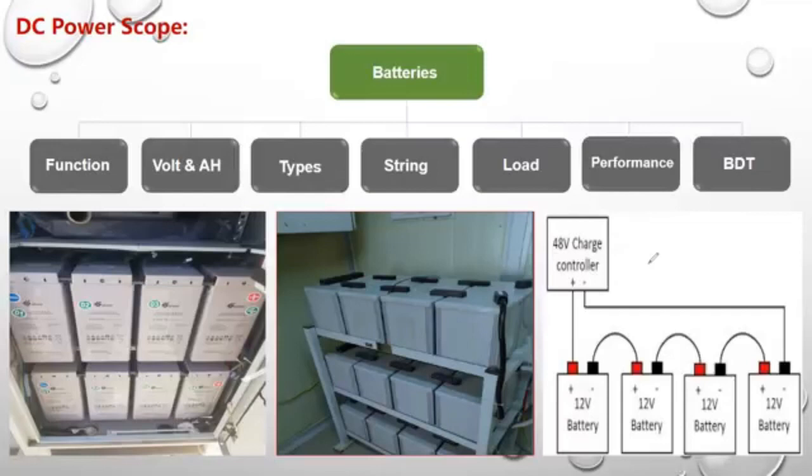Now, an important question that you must understand and know: why do we use DC volt in devices of telecom? AC cannot be stored in the batteries, but DC can be stored in batteries. So if I use, for example, AC, once the source that provides me shuts off, the network will drop.